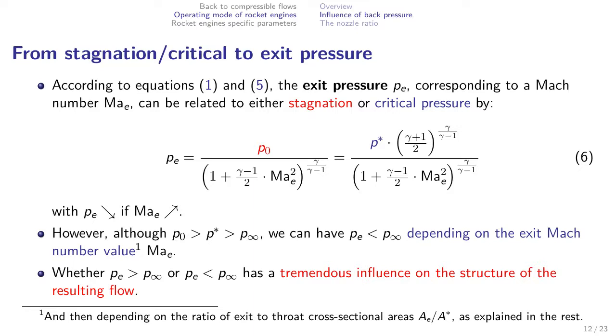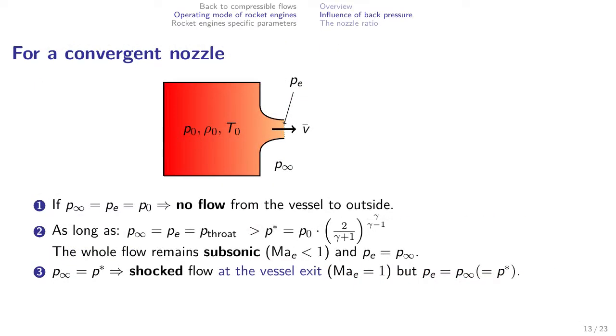We want also to increase the Mach number at the exit, and we'll get back to this because it also increases the speed of sound, and so the velocity for a given Mach number. Just imagine a simpler situation where you don't have any diverging part. You just have a converging part and that's it.